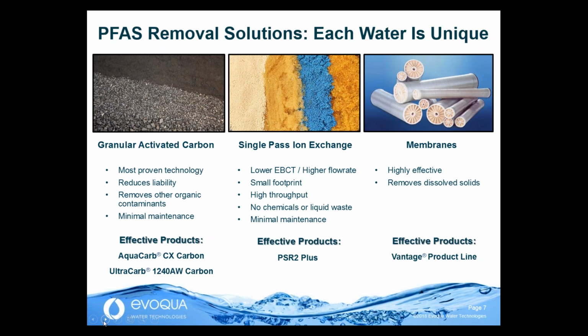So starting with granular activated carbon, GAC thus far is the most proven technology in the fact that it has the most full-scale installations thus far. It not only removes PFAS, but also will remove other organic contaminants in the water. But it is important to keep your finger on the TOC, or total organic carbon content, in the water, as that will compete with the PFAS absorption.